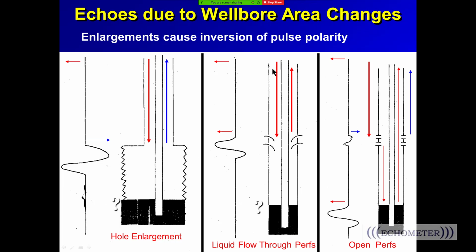Now this well has liquid flowing out of some top perfs, and it's showing the liquid level down here, and when we shoot the fluid level, there's so much liquid flowing in that you just see a liquid level at the perfs. This is unusual, because most of the time when you have a very high liquid rate that fills up the wellbore, the liquid level would likely be filling above the pump.